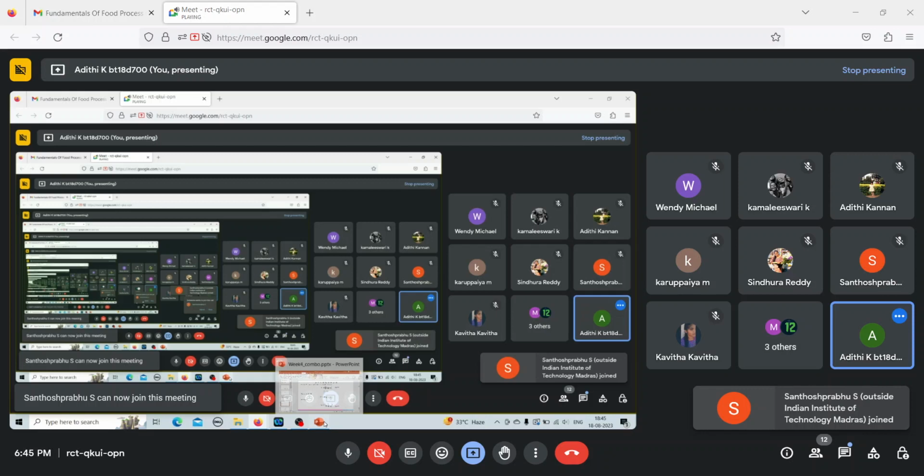So S into 2350 kilojoule per kg. I am converting kilojoules into joules, so I am multiplying by 1000. So 2350 into 1000 is equal to U, which we calculated as 1060.6, area which we calculated as 6.283 meters square, and delta T, which is already given in the question as 15. From there I can calculate what is S, which is 0.0425 kg per second, which is equal to 153.15 kg per hour. The answer is option D. Is this part clear? Any doubt in the sum?